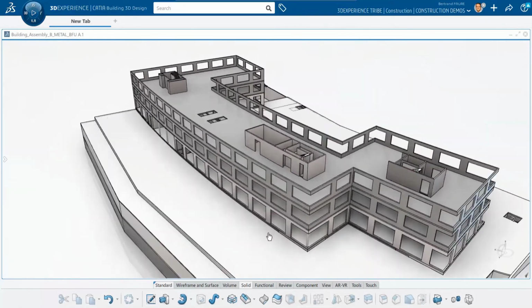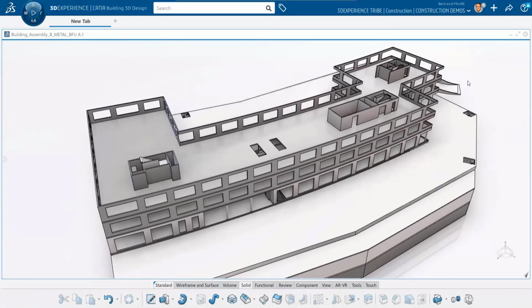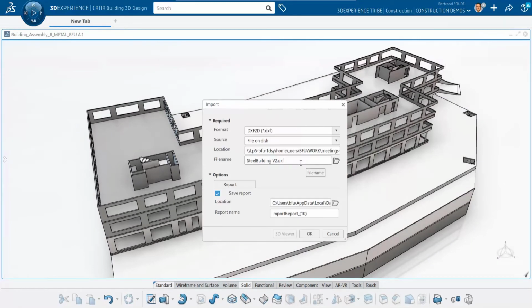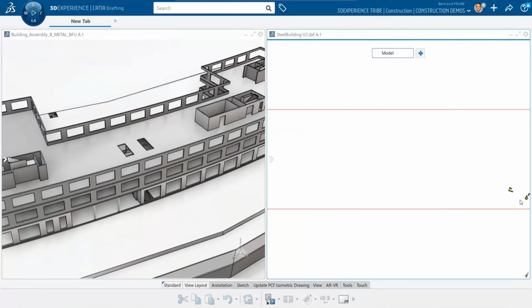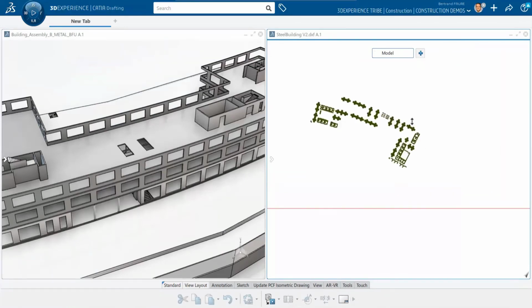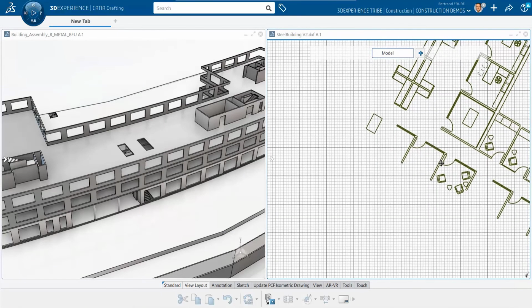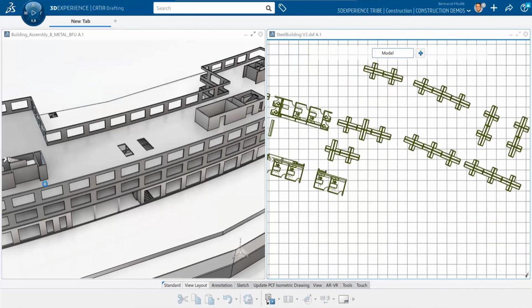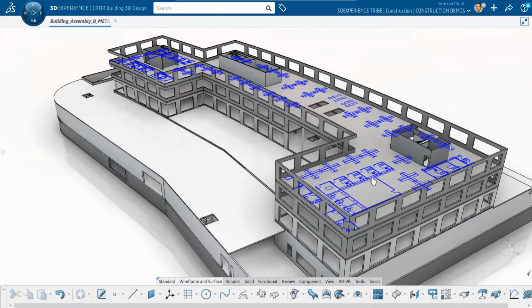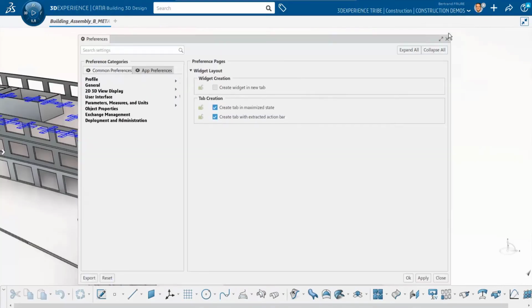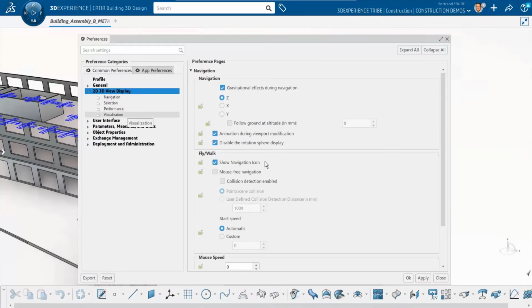Thank you, Raymond. Now we are back on CATIA, and I'm going to show how to reintegrate your drawing in 3D. The purpose, of course, is to display the drawing information as close as possible to the 3D context. And this is why I'm not putting the drawing on the Z0 plane, but I made a plane close to level 2 and I display the drawing on it. So what we can see on the screen now is exactly the lines coming from the drawing, and if I want, I can hide it behind the solid elements with this option here.